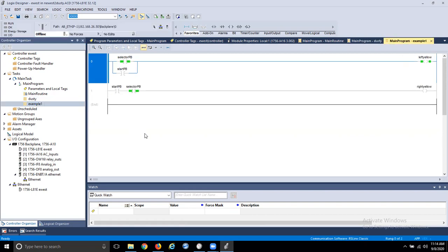And I don't remember what's in here. Okay. Selector, start, stop. And I don't think this is an active program. But this is what the PLC looks like. Now, if I want to change things or add things, if I go into favorites, this adds a rung, shortcut for adding a rung. There's more than one way to do it. This adds the branch, and in Click, it was control arrow down.